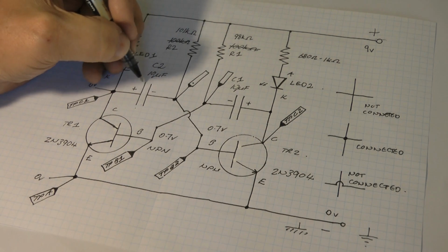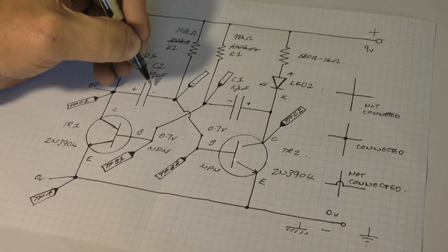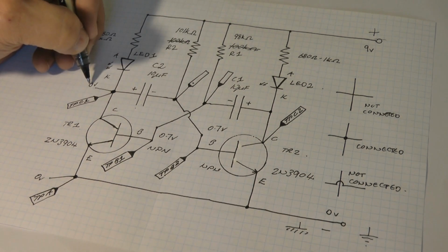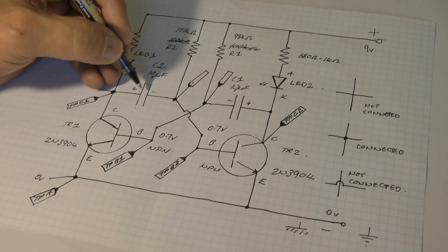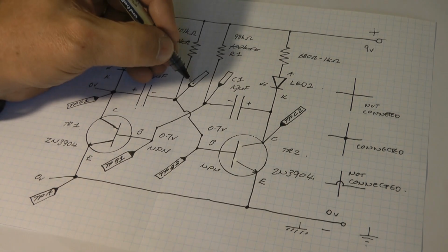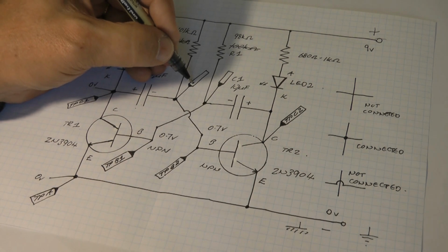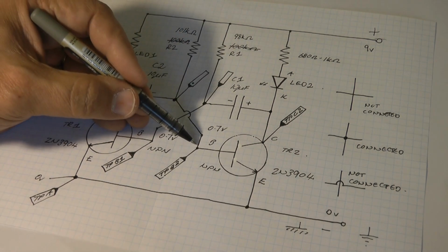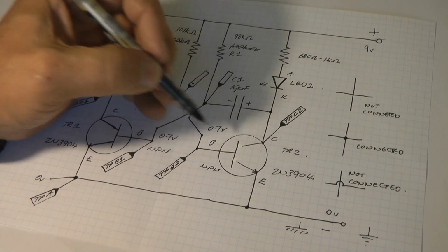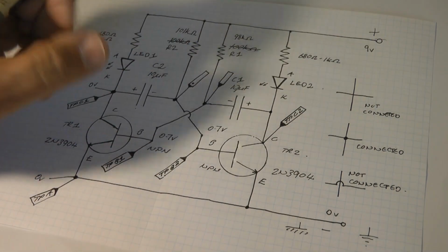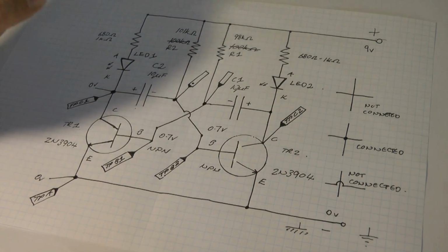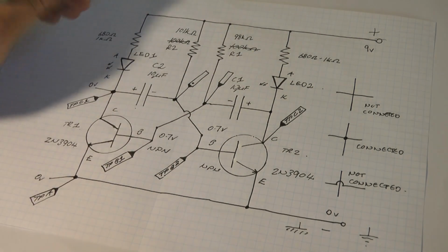So the minus voltage, whatever potential difference or voltage was present on this capacitor here, is now pushed into negative territory, because you've got 0 volts here, and this capacitor cannot discharge instantaneously. It does take a few milliseconds to discharge. So over here you see a negative voltage, and over here you see a negative voltage, which switches off this transistor. Because remember, when this little oscillator circuit starts up, you see some strange stuff, like it looks like both transistors come on, but the one is only on for like a very brief instant.